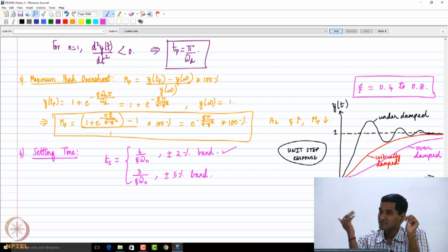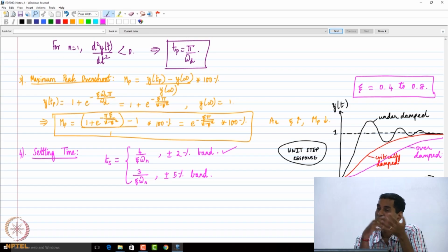That means that it's overdamped. The damping ratio is extremely high, because what is damping ratio? C divided by 2 square root of mk, for one degree of freedom linear motion. So if the damping ratio is very high, things will be very sluggish. So that's an overdamped system.